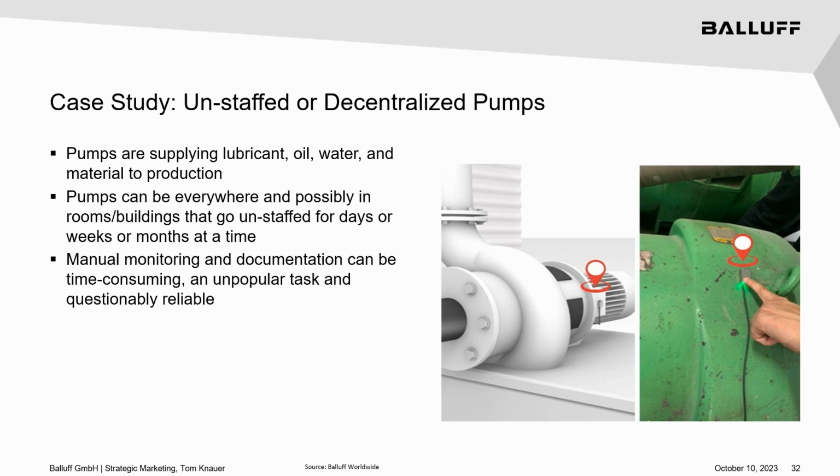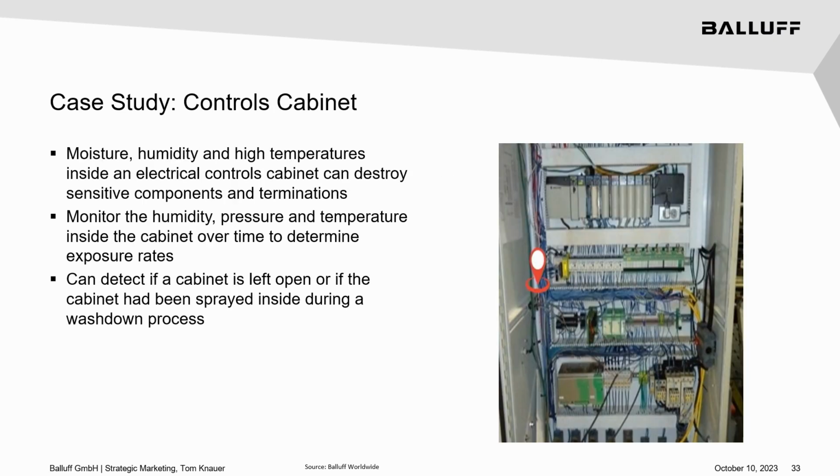By using condition-based monitoring, they can avoid those service calls out there when there's nothing wrong with the pump and be able to do it on a basis of when the pump needs actual maintenance, when things start to need to be checked and monitored because you're starting to see excessive vibration, you're starting to see excessive temperature, and only then do the maintenance on the system.